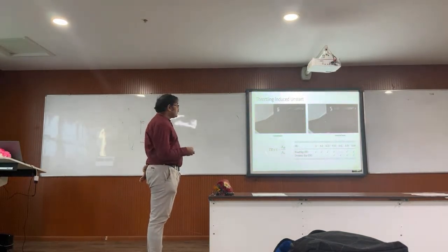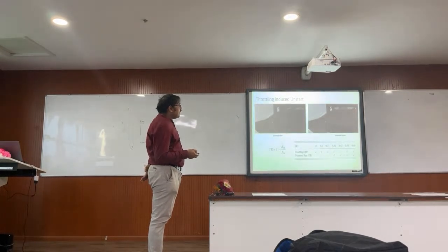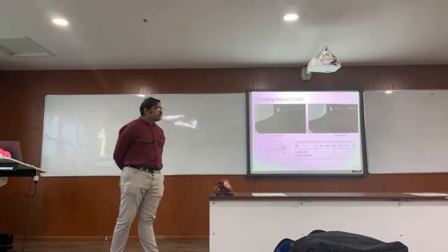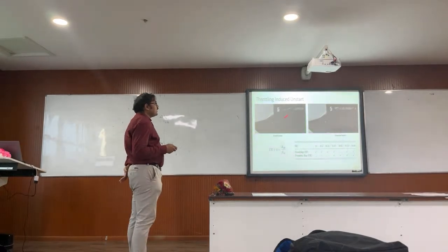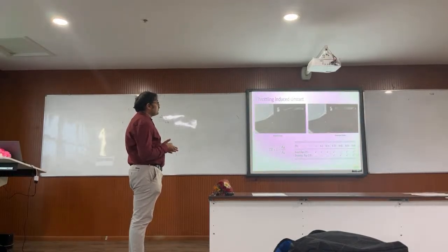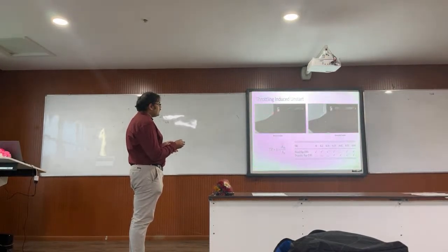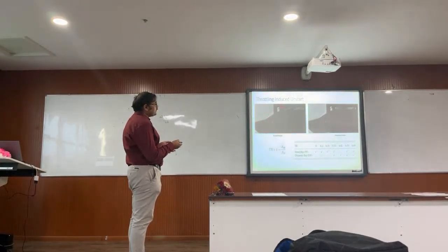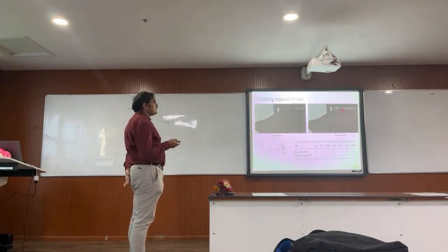This is a started intake, and I moved, and that is an unstarted intake. So you can see the started intake has the internal Mach 6 flow going on, and you have these shock waves. They provide the external compression. Then you have cowl shocks, which you can see here. The shocks you can see as very thin lines, and then you have supersonic flow. We can identify the flow is supersonic because we have a series of oblique shocks running in the back.